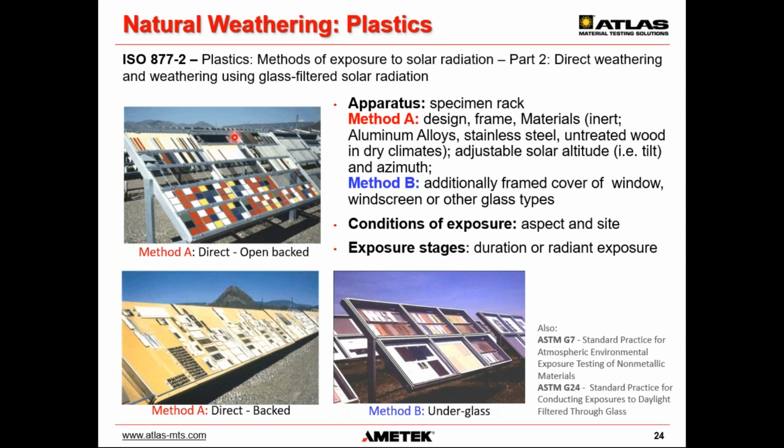For example, coatings typically use unbacked exposures. Some plastics or materials are typically exposed backed, as in their end use applications, which will produce different results. And finally, you have underglass exposures for interior applications, as well as automotive interior.